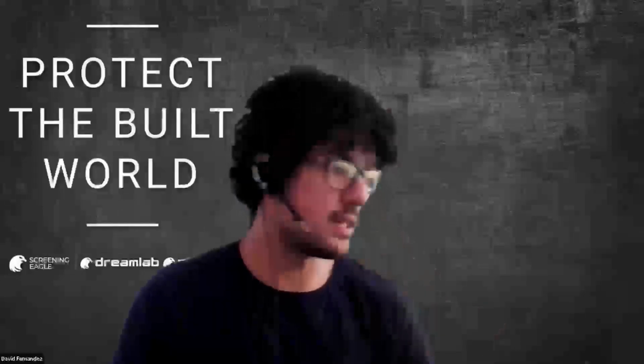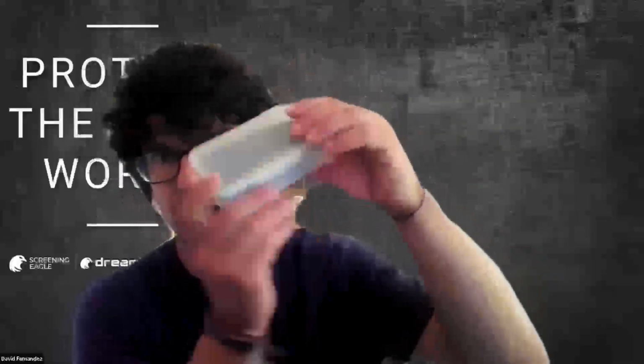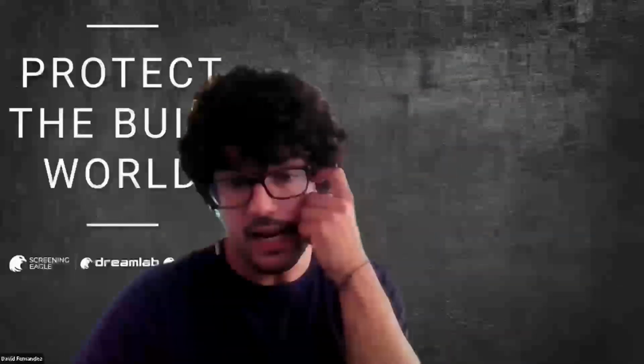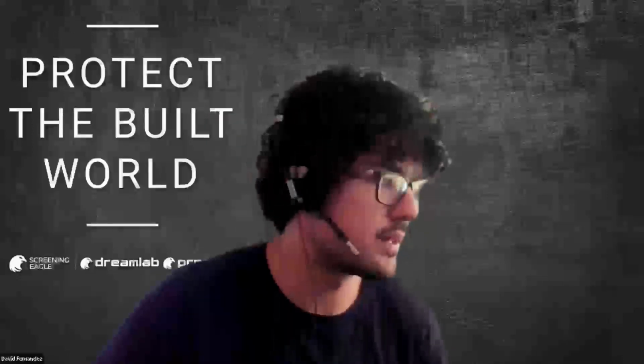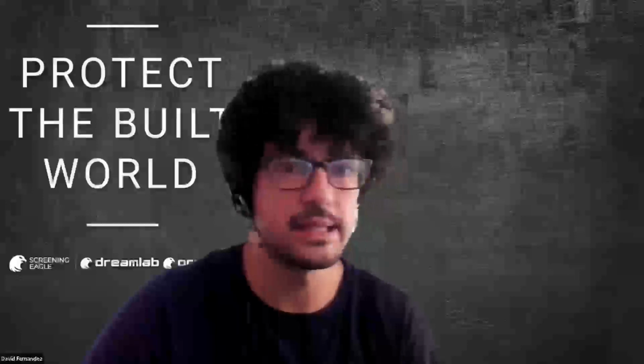It's normally destroyed. The concrete is not really ground. That's why you need to use putty. That is this sticky material that we also include with our kit. In these particular cases, for pile integrity, I will always recommend using this sticky material. You're going to have a much better signal.